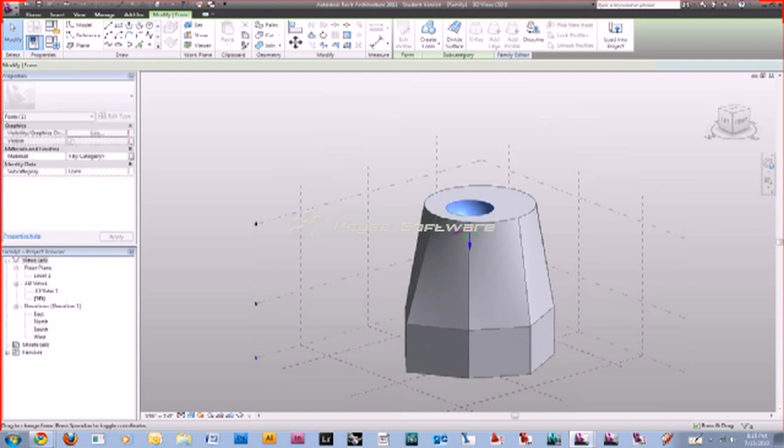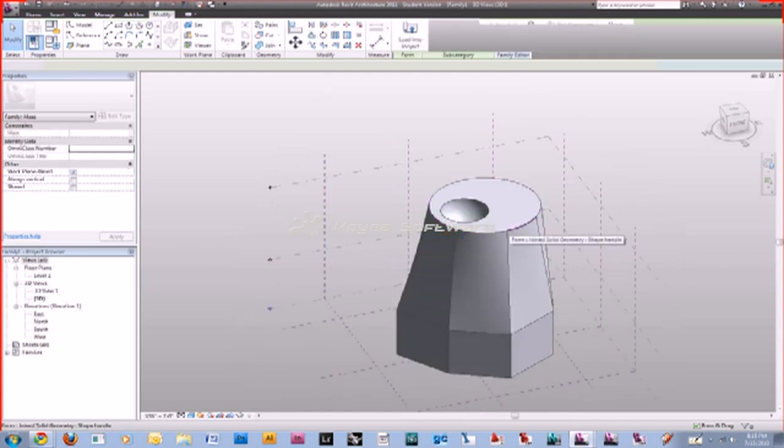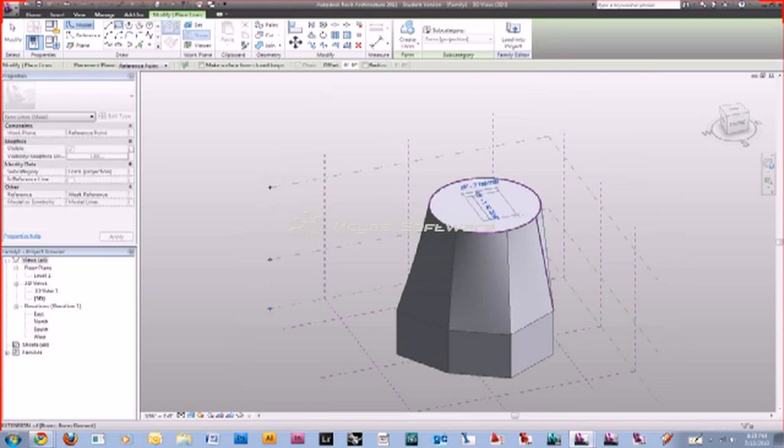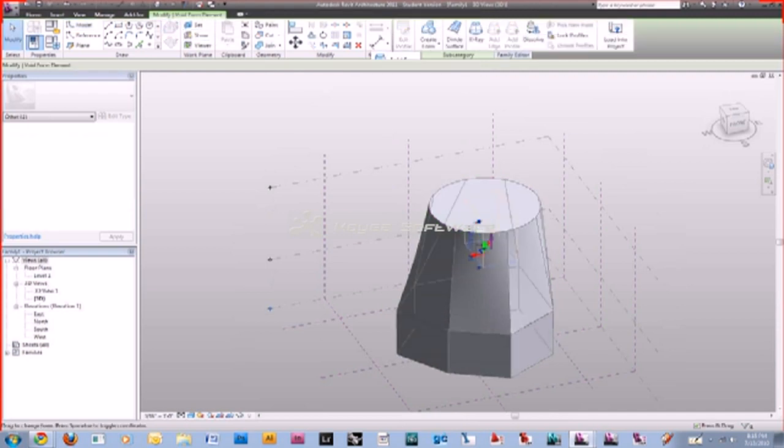I normally just use the first command. The first command is normally the one you're trying to do. I've seen this pop up too where it has five or six different options, where I was trying to create a sweep, but it thinks I was trying to loft or revolve those shapes as well. You may end up creating a shape you like a lot better just by going through those options really quickly and trying out different ones. Let me put a square so it doesn't look as nasty. Create void form. See, here it doesn't ask you because it knows you can only do one option. A square is not really ever going to be revolved.